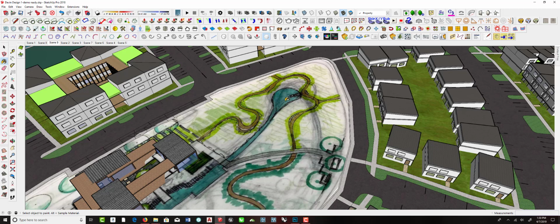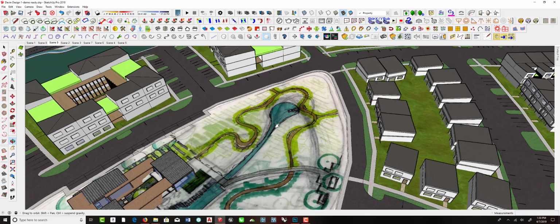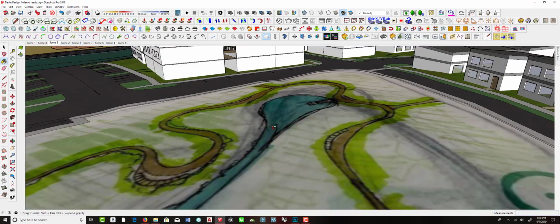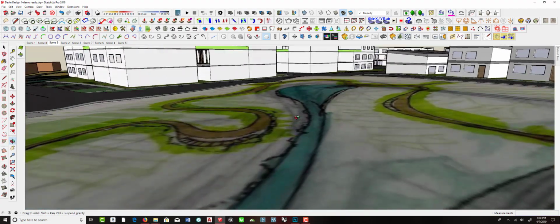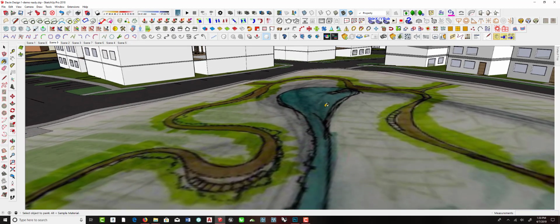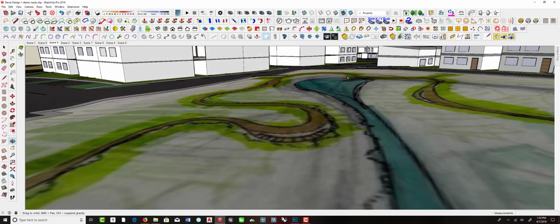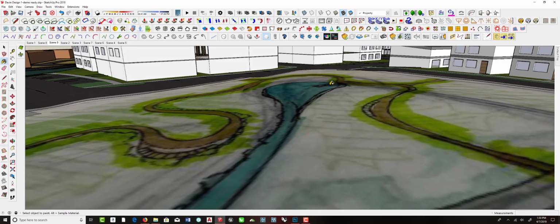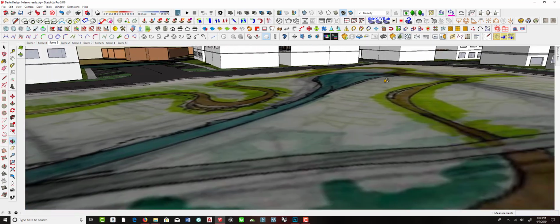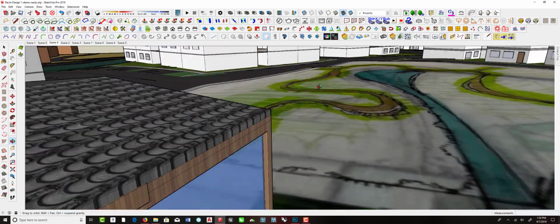Now, we talked about this in class about maybe even bringing this pond, tucking it in around here so that it's a little more related to a kind of exercise health center here. Also, when you actually put it down on the site, you can see that the water is flowing uphill, which doesn't work too well. So although in plan view at 2D it looked like this could work, you'd have to do some serious grading to make that happen. And even with tucking it around the corner, you can see we're going to have to change some grades.